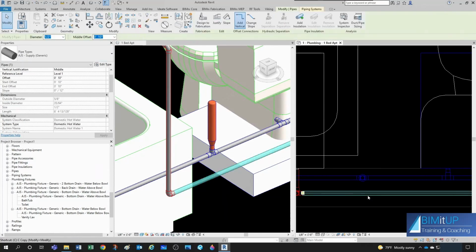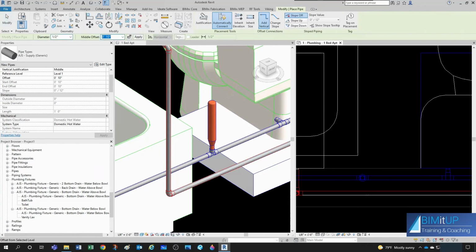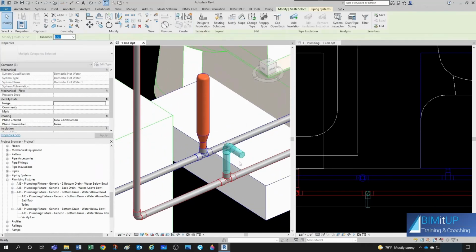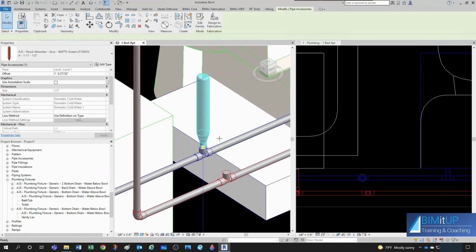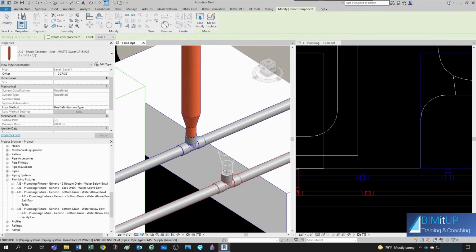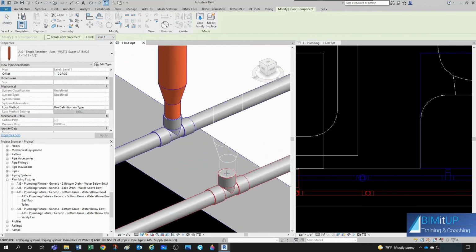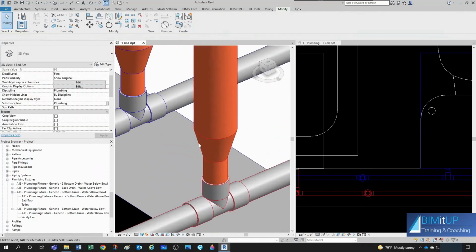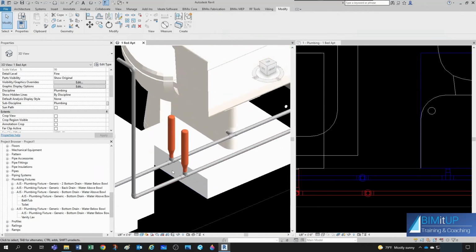So what I end up doing is simply do create similar. I do say 14 inches, and then I click here, and then I take it a little bit to the side, and then it takes it. So you can do tab select and just remove that, and then do create similar from this one, and simply drop it where it's supposed to be, which is right here. See the outline of the fitting turned red, so it's taking my system.